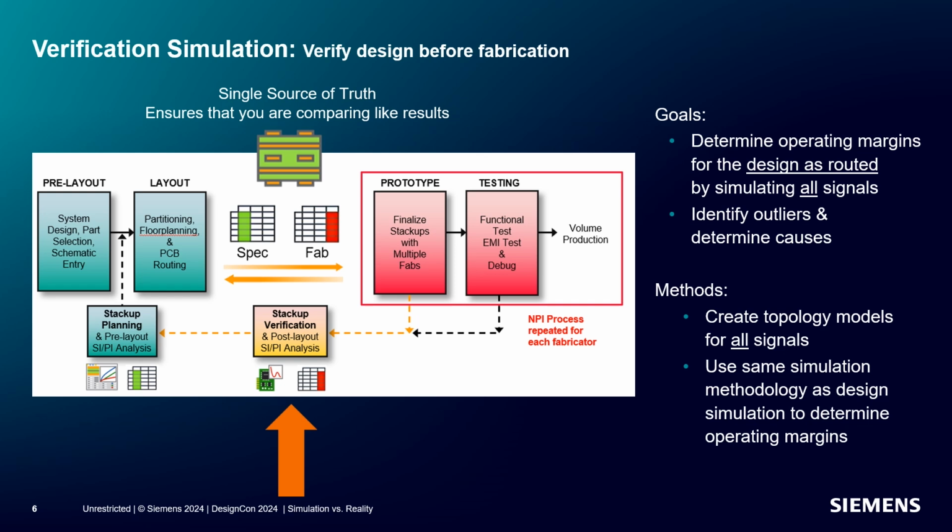So, when we look at the methods for verification simulation, they fall into a simple methodology. First, we create topology models for all the signals, and then we use the same simulation method as design simulation to determine our operating margins.